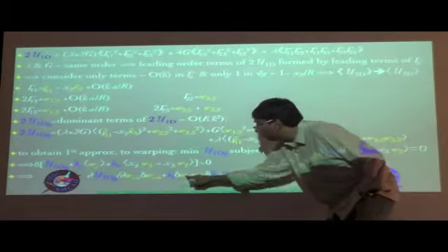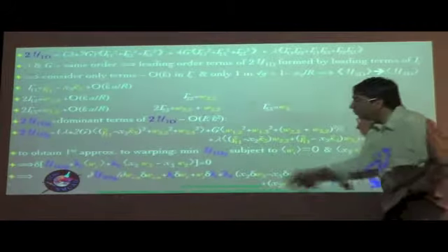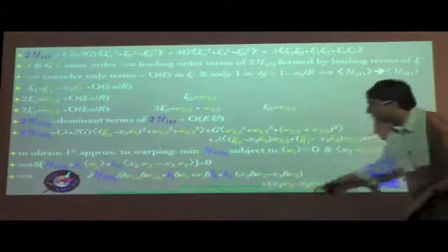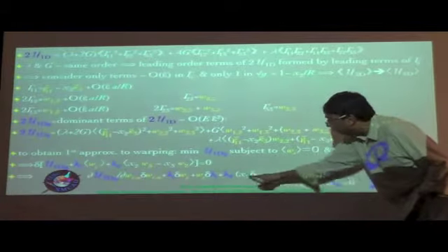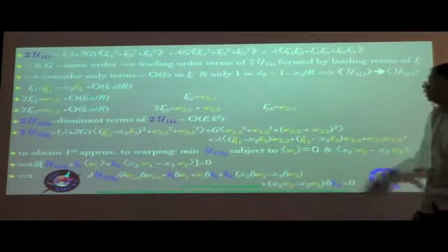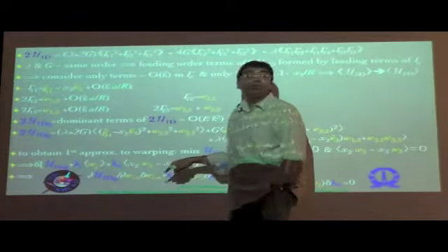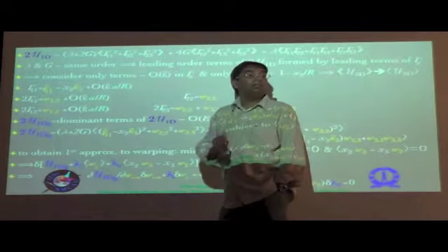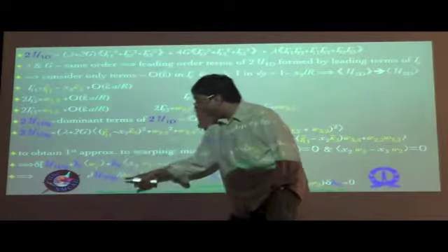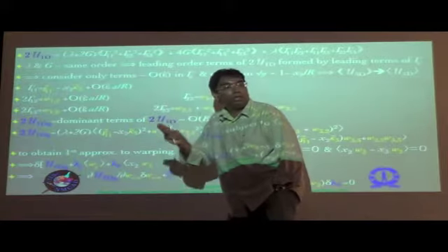So lambda j times the variation of wj, wj times the variation of lambda j, that is basically coming from these terms. And then from this term you have lambda 4 times x2 times variation of w3, x3 times variation of w2. So you see that through the constraints, actually w1, w2, w3 are coming in directly instead of in the form of their derivatives. Whereas through the energy, they are entirely coming in terms of derivatives with respect to the cross-sectional coordinates.